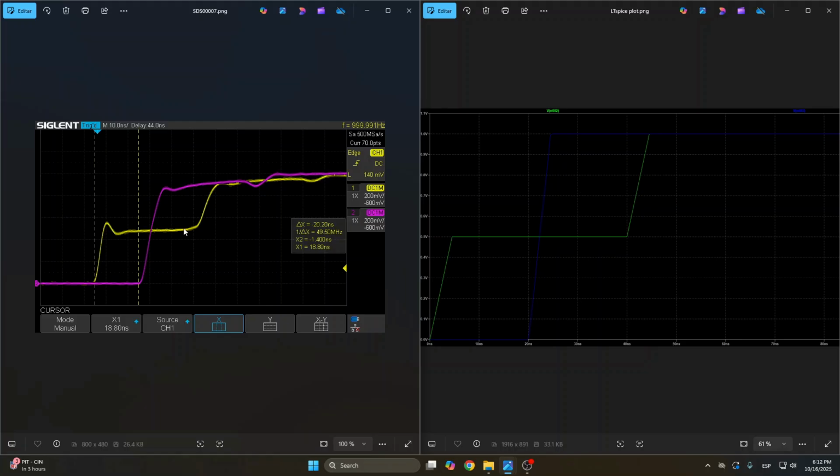So yeah, I think this tells us that even using a pretty low-cost prototyping service for PCB manufacturing, you can achieve pretty good results in terms of characteristic impedance if you follow the manufacturer's guidelines and stack up, and you design your traces to have the right width and the right spacing to the ground layers and all those parameters that we showed previously using the KiCad's calculator tools.